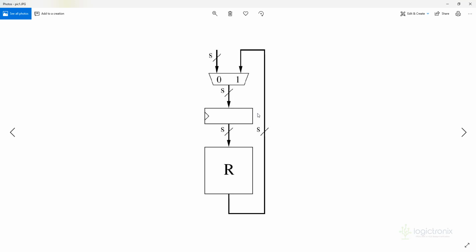So this is the basic iterative architecture. We just give input here, and here is a register, and here is a round, and it can be a round of any function or any algorithm. First, this line will be selected, and it will pass through the round, and the output of the round will be fed to the input again through the register. This is the basic iterative architecture, and it will occupy the minimum amount of area because it has only one round, and its throughput will also be low, and it will have the worst performance.